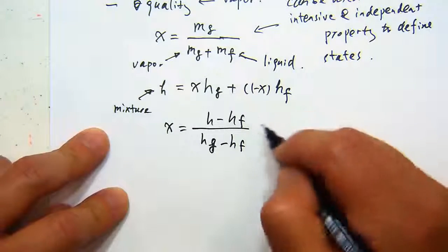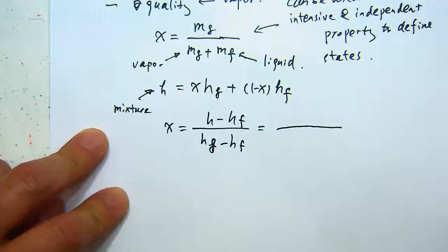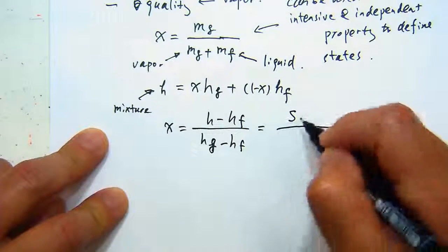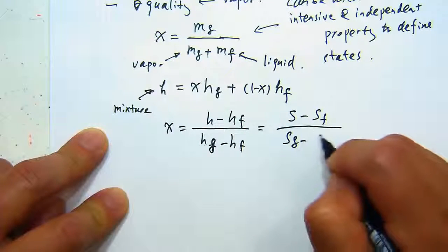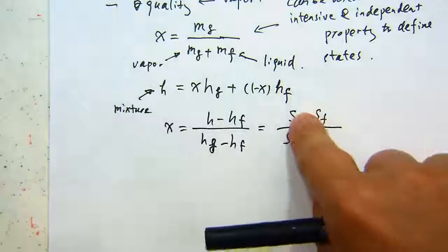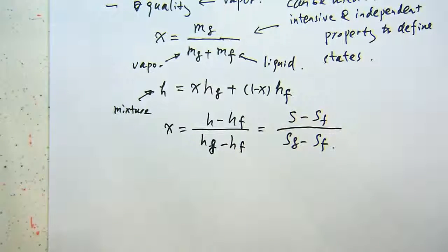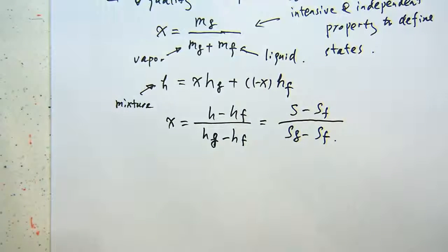All right, so that's the one. And also, in other cases, you can figure out the entropy of the process. So that's similar. If you're going through an isentropic process, the start and end will have the same entropy, and if that end state is in the saturation region, then you can use that to calculate the quality of the mixture.